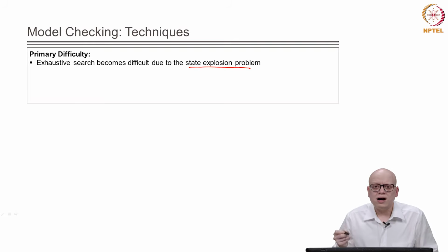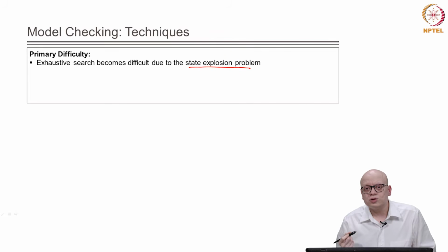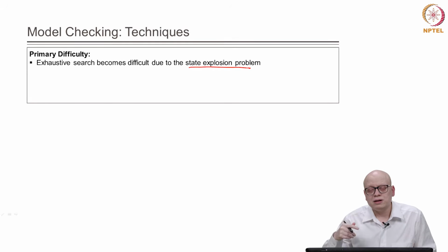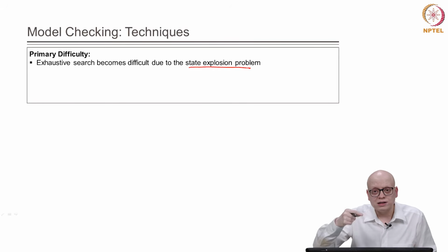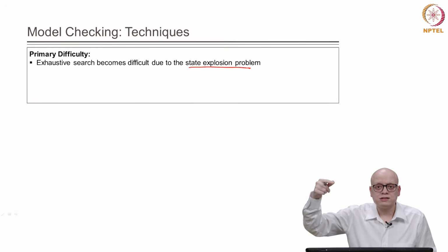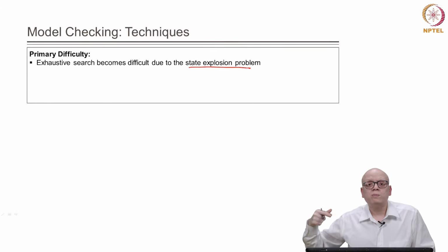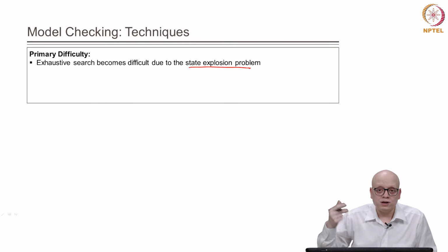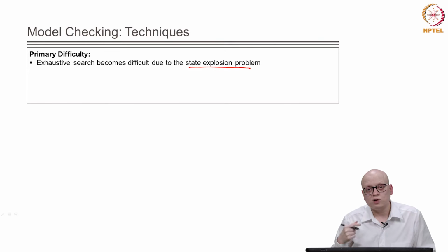Earlier, what researchers or VLSI designers tried was to enlist various states, and then, using graph traversal, given a starting state, various states were traversed, and the properties were verified based on whether a state is reached where the property is not valid.